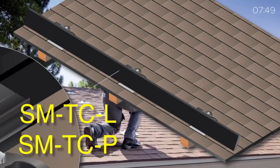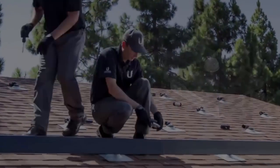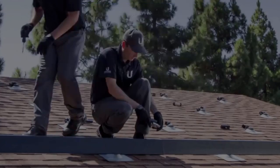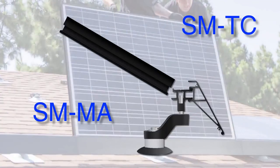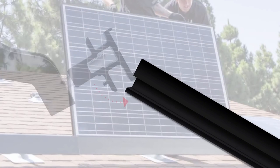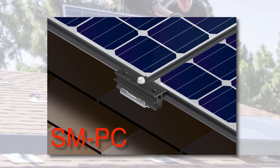Portrait and landscape trim covers run along the bottom row and are secured by a lock mechanism. Insert panel connectors with arrows lined to the marks on the back of the trim. Panel connectors join panels along each row. Proceed to hook and lower panels into the bottom row of mounting assemblies. After scanning the QR code into the customer site for the SunMax mobile app, insert mounting assemblies and panel connectors along the top side of the panel to stabilize and bond adjacent panels throughout the array.